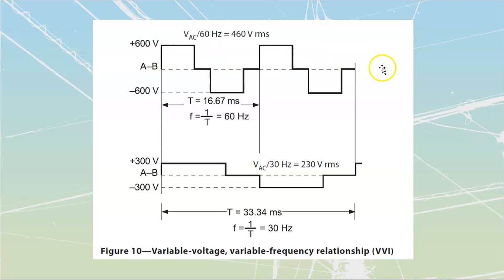As my frequency goes up, so as I chop more rapidly, I'm going to have to raise the amount of volts. Remember that the volts over here are going to be covered by my converter section, and that my frequency, the amount of time, is going to be contained by my inverter section. Those two are going to work together through the controls that we have inside of here.